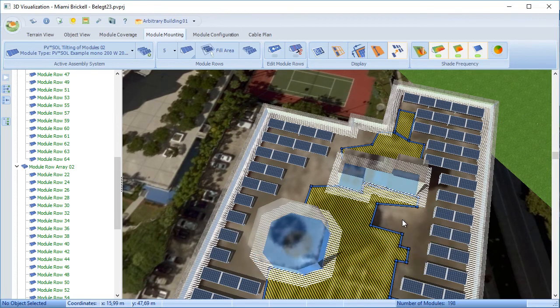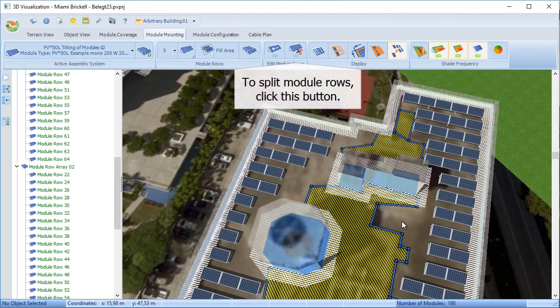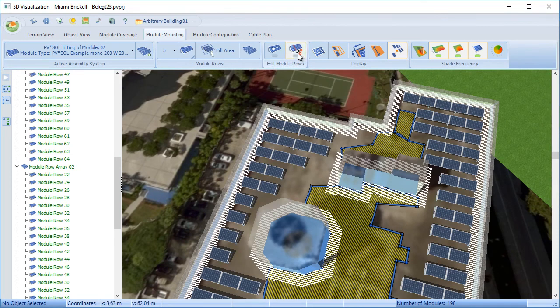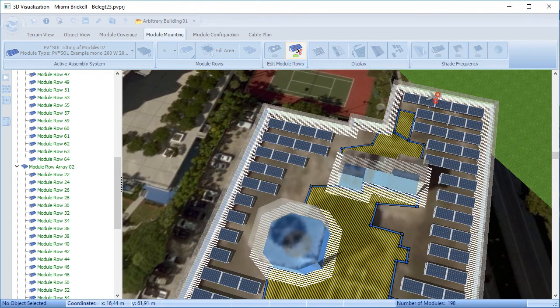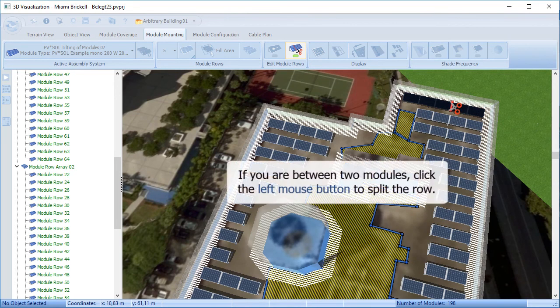And now we're going to illustrate the cutting of frame systems with that icon with the scissors. And once that's selected, all other features are disabled with the mouse, and now you've just got this pair of scissors which you can use to choose which array to cut, to separate, as it were.